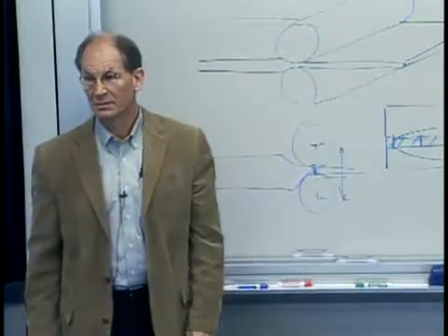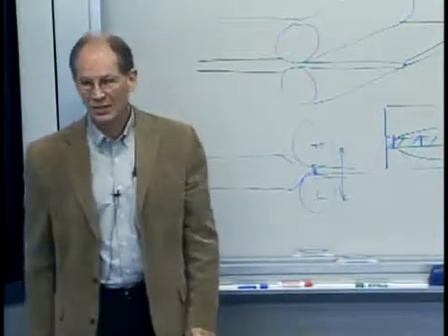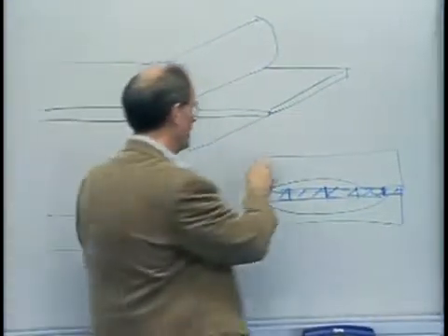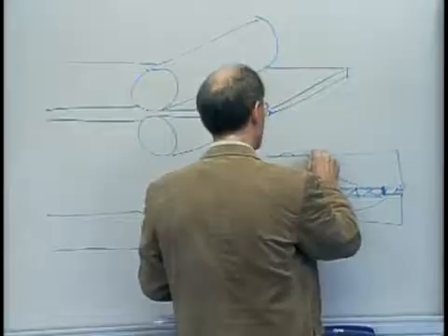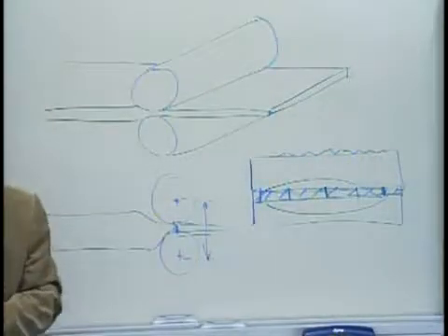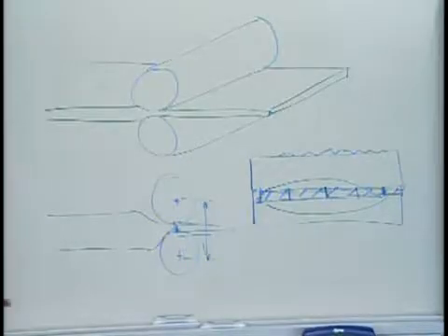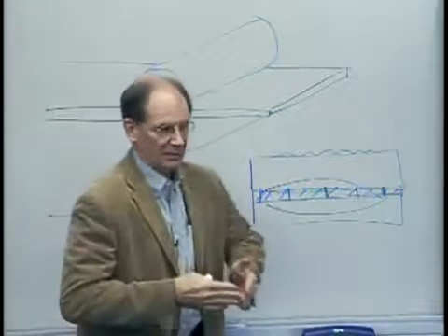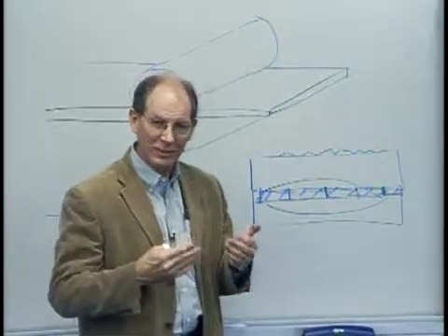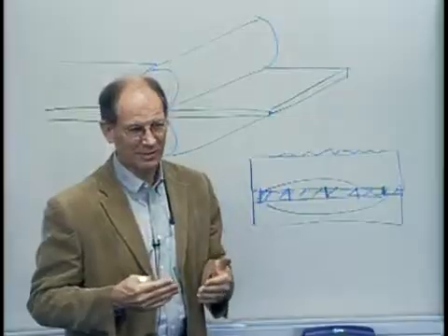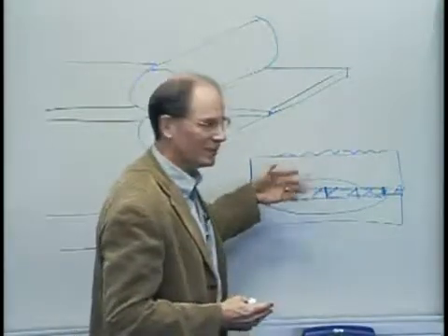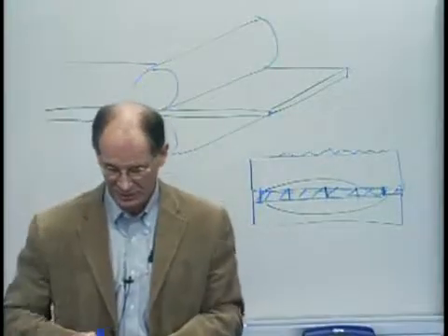It'd be like locally heated through heat. Yeah, in fact, that's what is done to get small displacements, to not arbitrarily, but to put some different profiles on that. You'll locally heat it or cool it in response to feedback to slowly move the tool locally, a little bit fatter here, a little bit less there. You can imagine if you only need something like 10 microns, it doesn't take a lot of heat. And yes, indeed, you're going to say, oh, how localized can that be? And that's the trade secret they won't tell anybody about.